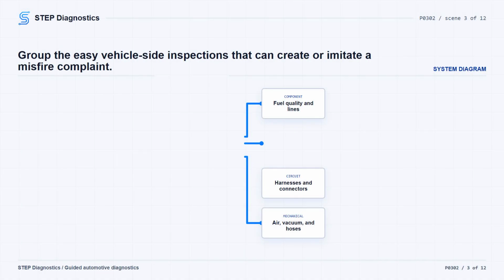Next, make the inspections that can catch the simple problems. Check the harnesses for damage, chafing, and routing. Check fuses, circuits, connectors, and component connections. Then look over the vacuum lines, air intake, and hoses for leaks, restrictions, damage, blockage, or routing problems.